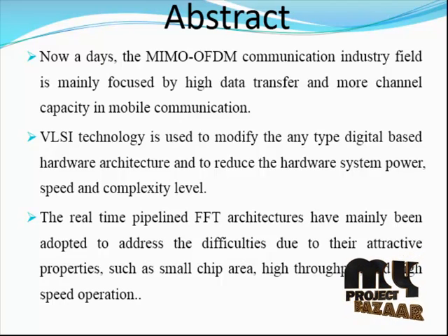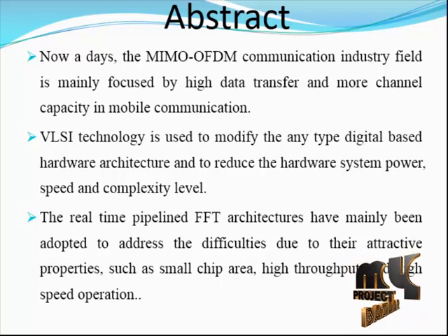In the Radix-2 FFT architecture, it is a common observation that one half of the data do not involve complex multiplication at all, while the other half indeed involves complex multiplication. Hence, it has the opportunity to reduce the arithmetic resource of the conventional complex multipliers by a factor of 2, leading to 100% utilization. It is ideal for two consecutive complex input data to contain a complex number which needs to execute complex multiplication. If so, we can minimize the reordering memory requirement while reducing the arithmetic resource of complex multipliers by 50%.